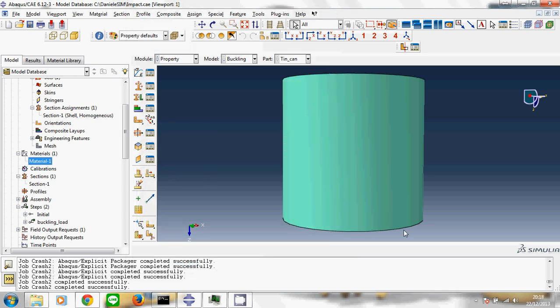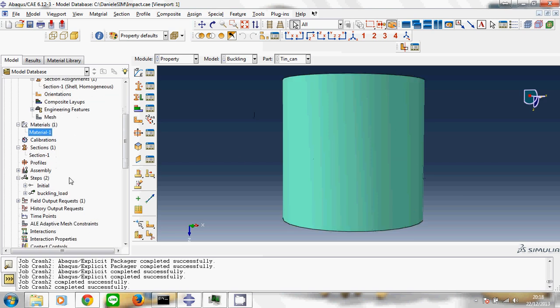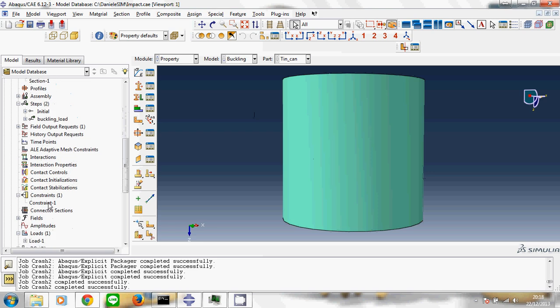This is a really simple analysis. This is not capable of taking into account nonlinearity like material, geometry, load, boundary condition. So there is no possibility to model, for example, a contact. This is just an analysis that we need to have a first number, so that we know the structure under this load will fail.